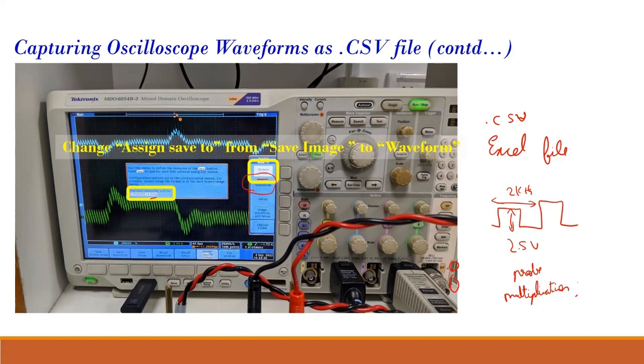So this is also provided. Similarly, the measure feature is also provided. This is used for changing the vertical zoom. This is used for changing the vertical position, to bring the trace up or down. Correct? This is now, suppose, 2 volt per division. If you change this, you can make it 4 volt per division. All these are there in the oscilloscope.